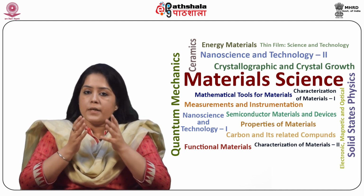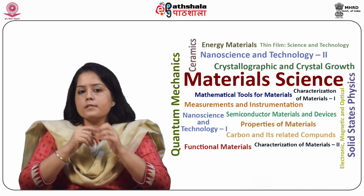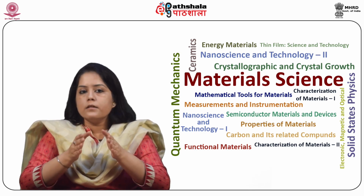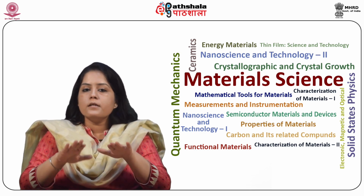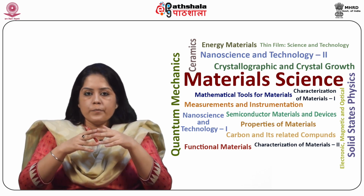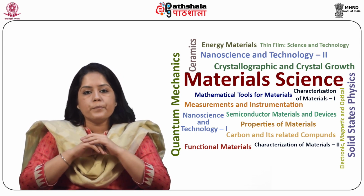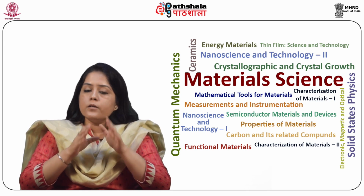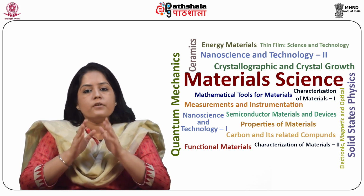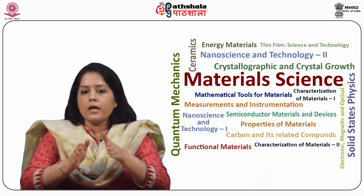So, the basic applications of these alloys are: first, force actuators, that is, they exert force over a considerable range of motion. Second, in joining, that is, in cylindrical sleeves joining tubes. Third, they are used in proportional control, that is, the valve controls the rate of fluid flow by careful heating.